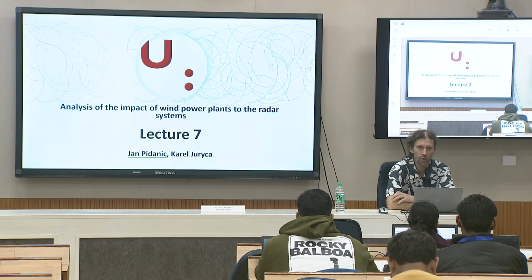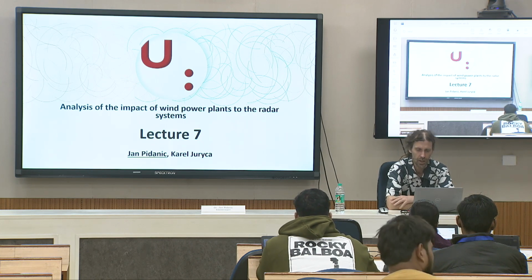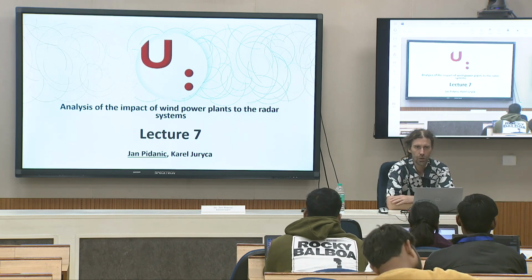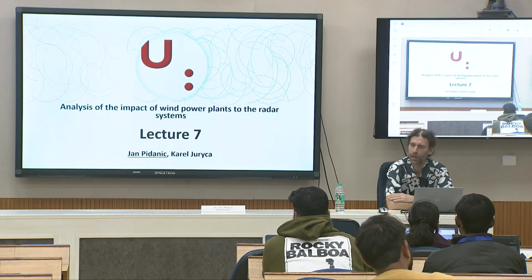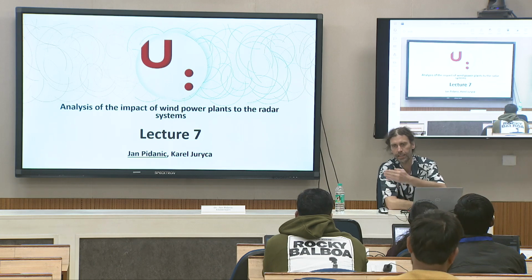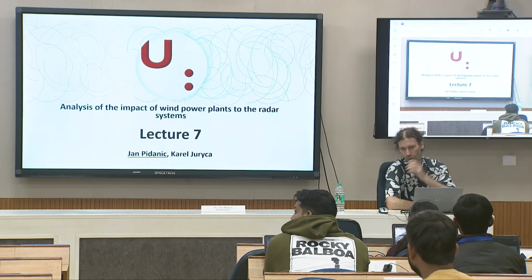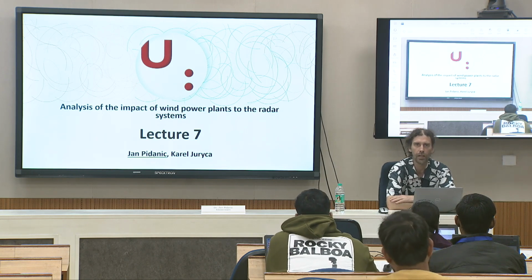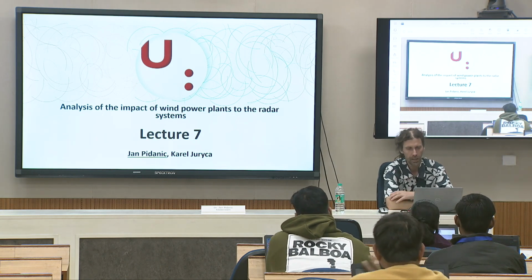So I will introduce you during this session the AMPD peak detection algorithm that we use for detection of the DSC component in the spectrum, and the prediction of the DSC component in the next time instance will be based on the UKF, the unscented Kalman filtration method.